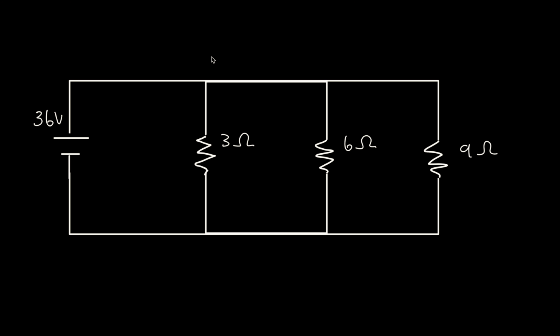So, over here, when we're trying to find our total current, we need to find the current flowing through each of these resistors. So, we're going to be pretty much solving them using Ohm's law and treating them separately. So this will be R1, R2, and R3. So let's start with R1 over here. So we know Ohm's law, voltage equals current times resistance.